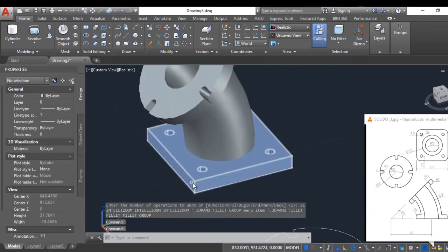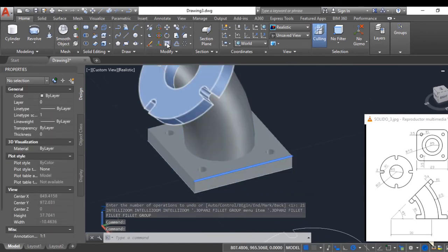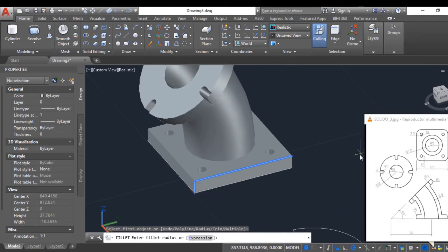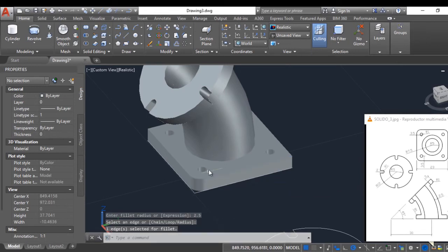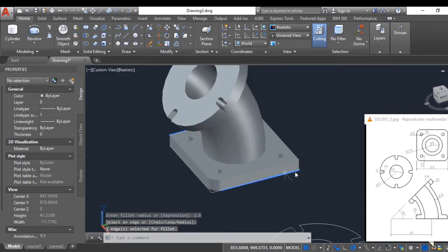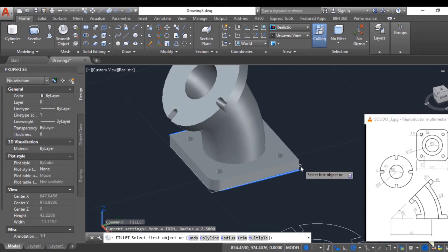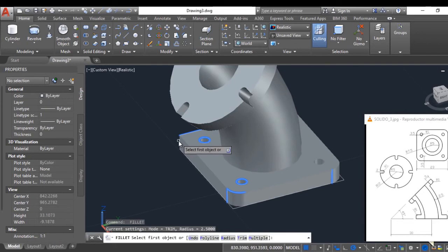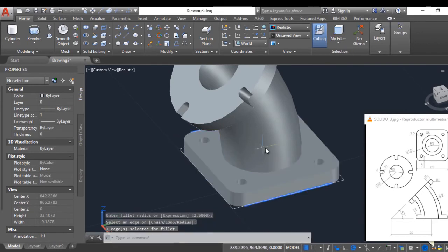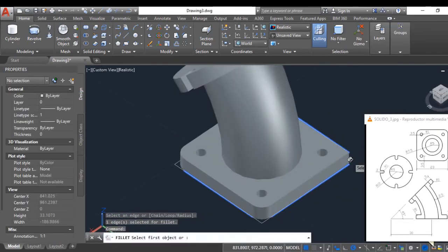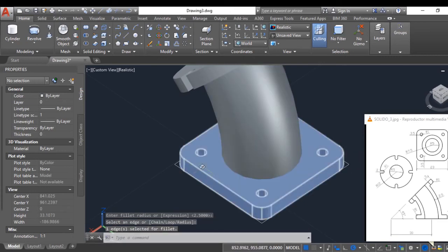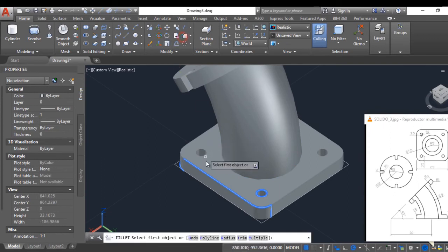We are going to do the beveling. First of this part here, in this part of here, we are going to give it a value of 2.5. I press enter, we are going to do the rest of the bevels, and this one here, you already have the measurements, I just press enter, and again enter. Same here. This beveled, I hit enter twice. And here we are also going to do this bevel, I press enter twice.